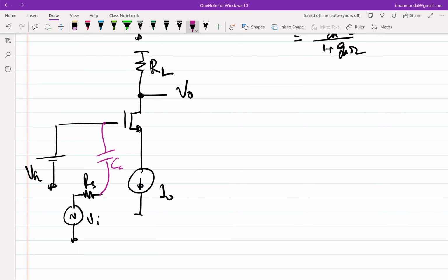Will this work? But gain will be 0. Why? Because constant current will flow, so incremental change will not happen. Okay, that's obviously one case. We'll get to the output side. But what about the input side? Is the input side behaving properly? The DC source is directly connected to the gate, so the gate voltage cannot change, right? So then what should I do?